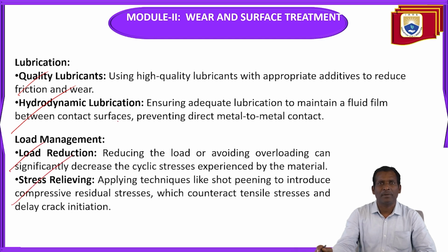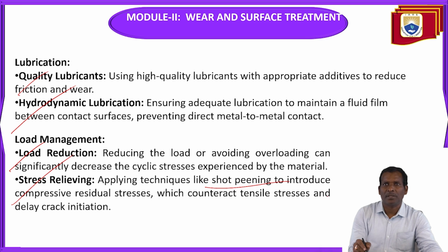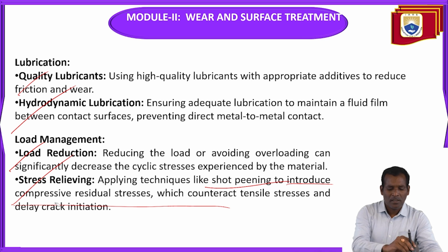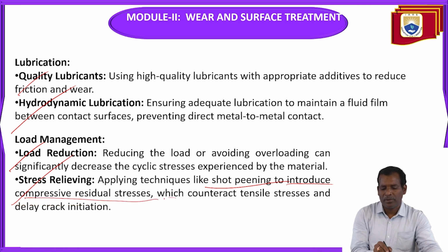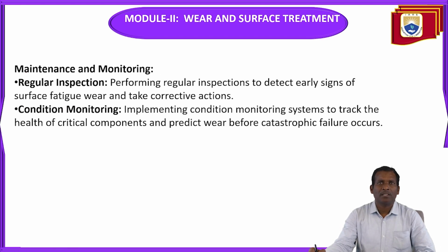Similarly, stress relieving. Applying techniques like shot peening, which we have already seen in the previous slides, introduces compressive residual stresses, which counter tensile stress and delay crack initiation. Then maintenance and monitoring.